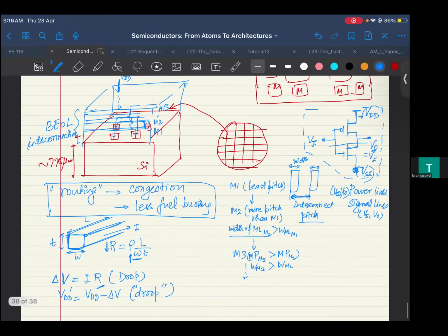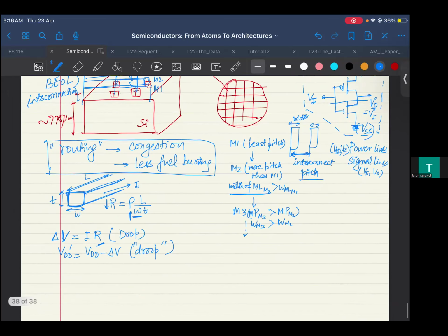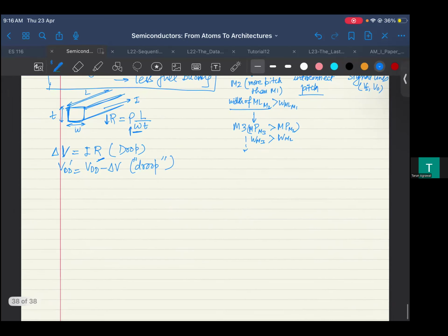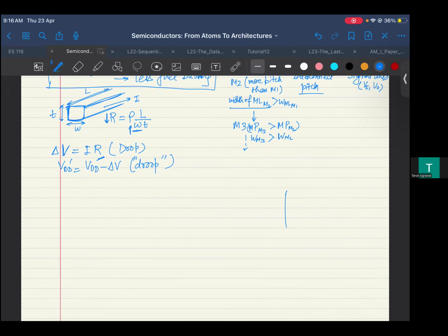And that is why industry thought, okay, why do we need to provide this line from the top and have to go through these 13 metal layers and reach there? Is there a much smarter way to do that? And that resulted in a thinking that, okay, is it possible that I have silicon, and when I'm making transistors on top of that, I'm not using, for example, the 775 microns of silicon? Because only this part is used, let's say whatever is the active channel part, when I'm making these active devices, so this part is unused.